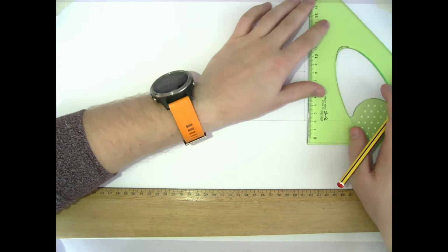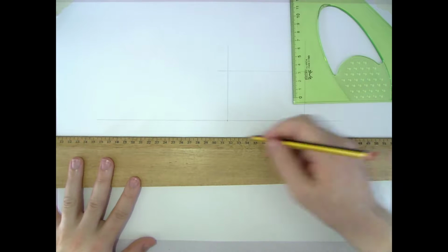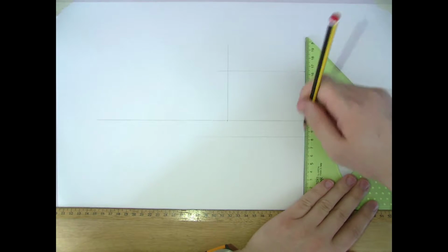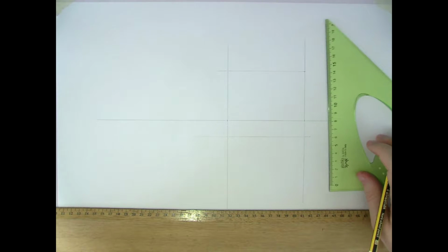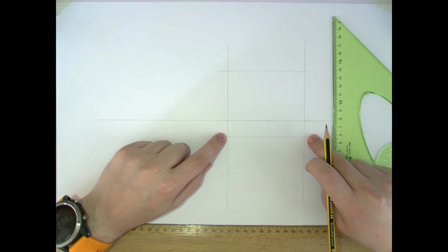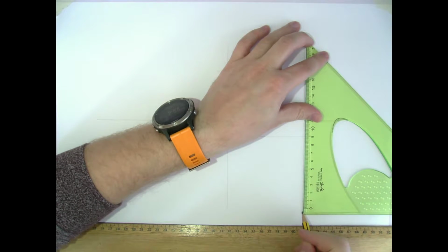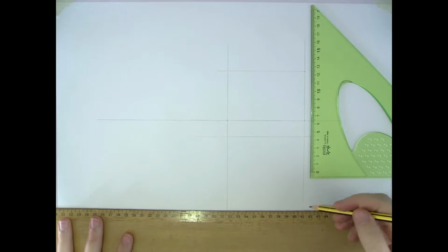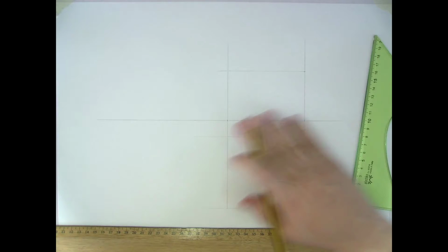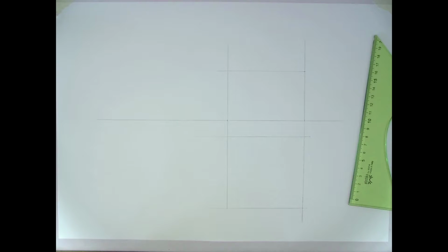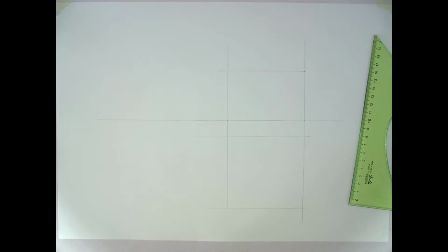The plan is going to go down directly below it. I'm going to put just a gap of 20 millimeters between the two so that there's some distinction or separation. So the width is still unchanged, and then the distance down here is going to be coming down 90 millimeters. So my elevation and plan will fit into these two boxes. The auxiliary view then will be projected off that, and we'll look at that later on.